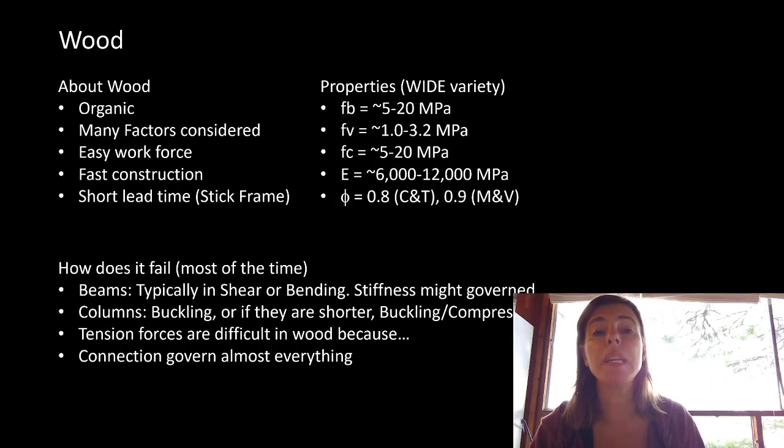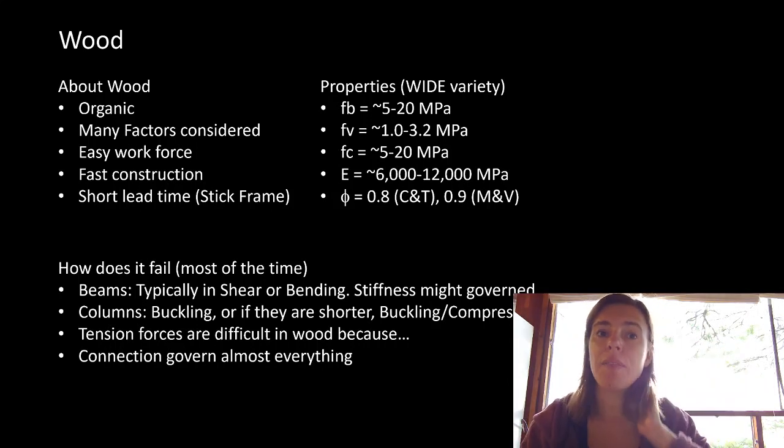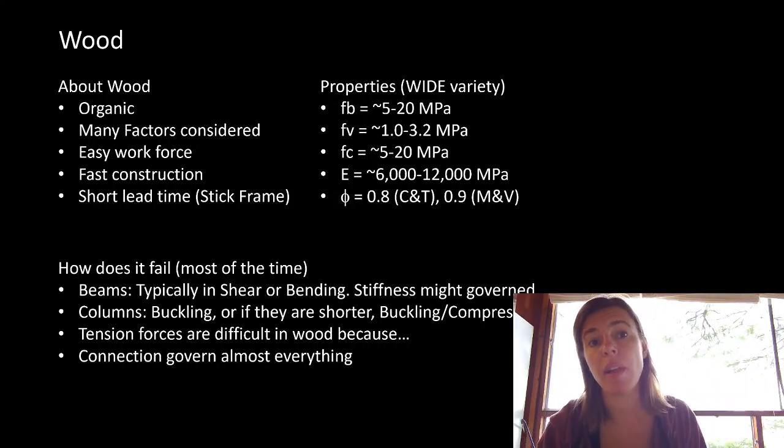Tension forces are really hard to do in wood because connections govern everything in wood. Moment connections are hard, and tension connections are hard in wood. So often if we have something in a wood system that needs a lot of tension, we might have a steel element within that part of the system.